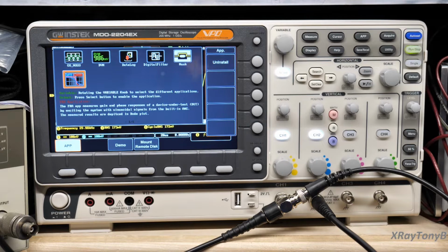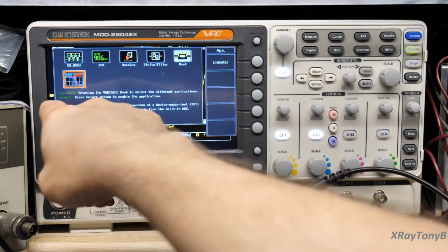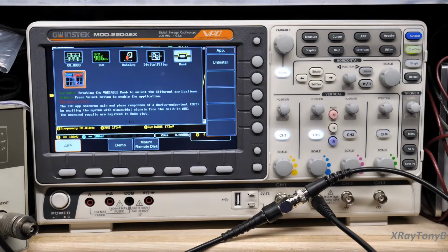So for instance, if you have the tone controls turned off of the flat setting, you'll see that at certain frequencies the gain will change, because the treble could be turned down, or the bass could be turned down or turned up. But if you set everything at flat, technically you should get the same gain across the board from 20 hertz up to 20 kilohertz without it modifying the signal, amplifying or attenuating it. It should be flat the whole way through.